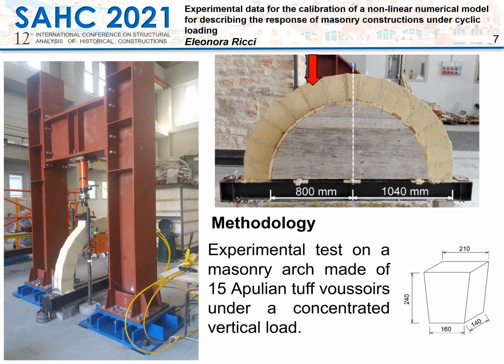An experimental test has been performed on a circular arch made of 15 blocks of Apulian tuff, whose geometrical dimensions are shown in this slide. The test has been conducted in displacement control and was performed by putting the arch under a steel frame used to support the loading device.